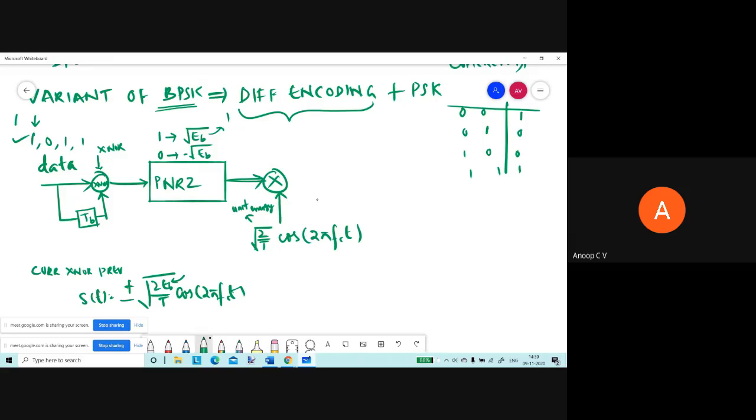So this is just like our binary phase shift keying, right? Either a symbol 1 will be represented using a positive RF pulse, positive in the sense of an in-phase RF pulse, and symbol 0 will be represented using an out of phase RF pulse. So this is actually the modulated signal, you can call it S of t, right? So this is a modulation.